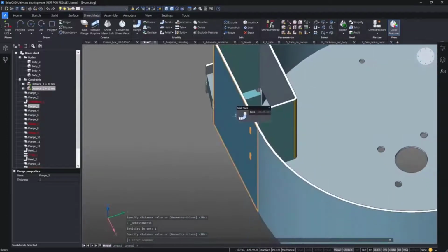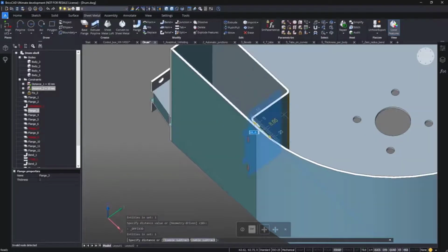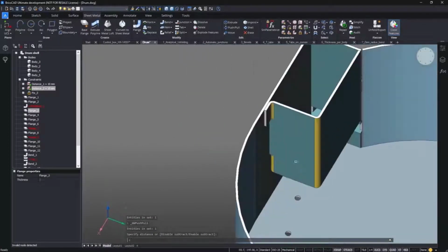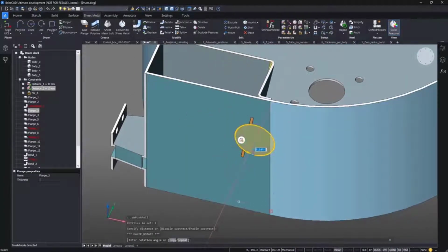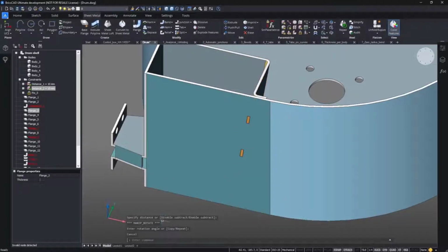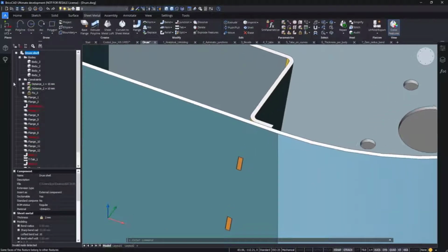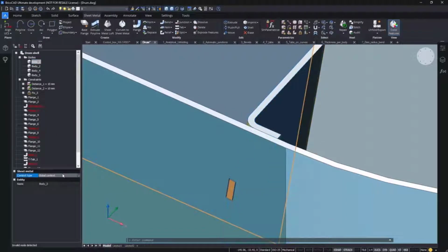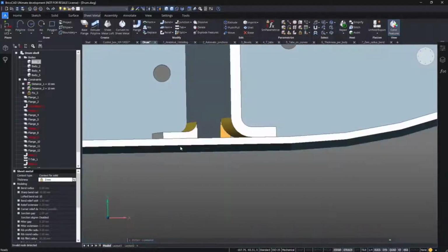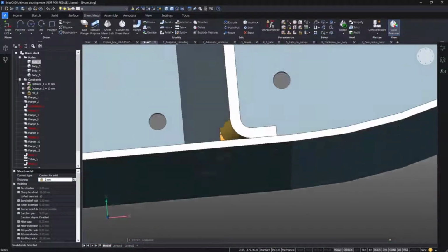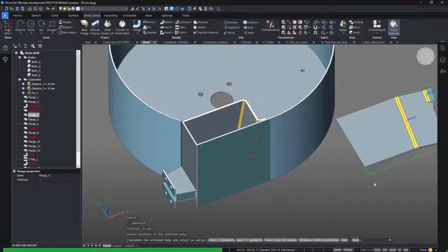And now, look at this. By moving the flange by push-pull, the tabs and slots are moved accordingly. And now, even stronger. Even in rotation, the tabs and slots are moved correctly. Wow, I'm blown away. Then, thanks to the new capability of V21, we can change the thickness of this part particularly. And you can see that tabs, slots, dimensions, and the design intent are respected perfectly without any collision. And of course, we can unfold.